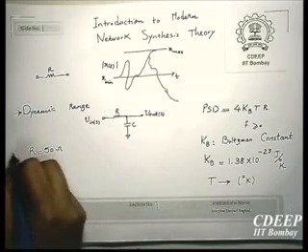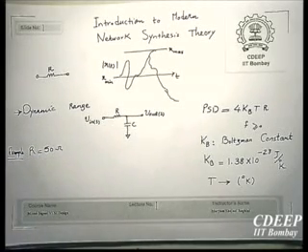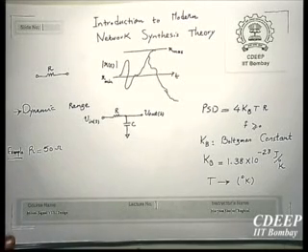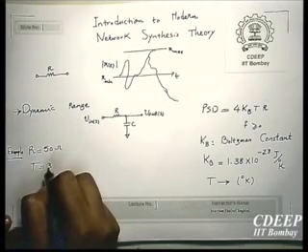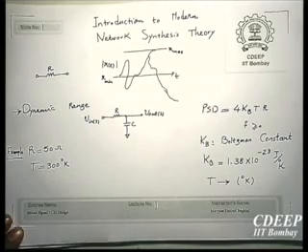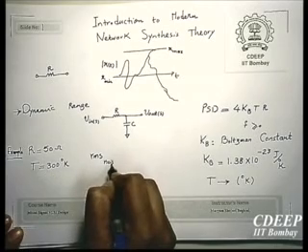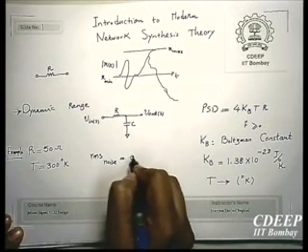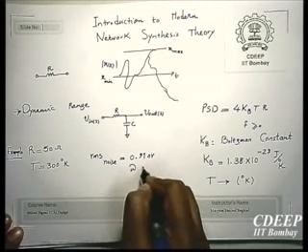just an example, I say 50 ohm because this is one of the standard values which is used in many RF systems. So at room temperature, which is 300 degree Kelvin, effective RMS value of noise will be 0.91 nanovolt at 1 Hertz bandwidth.